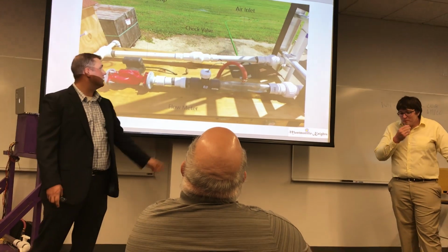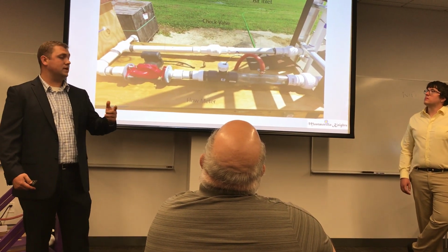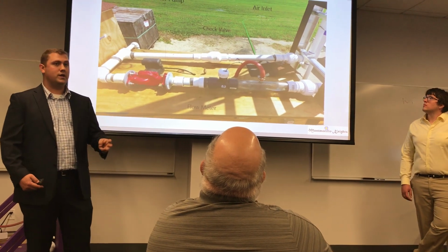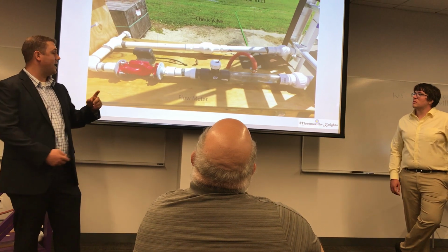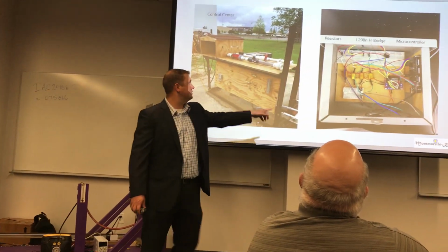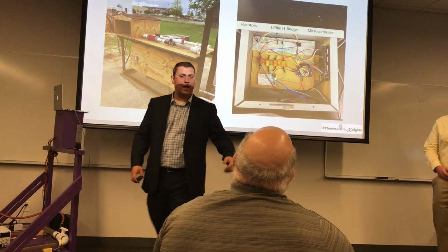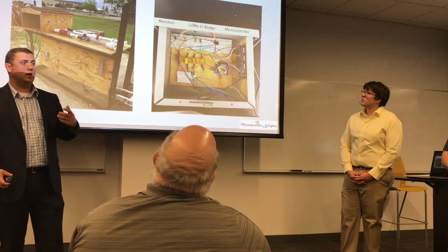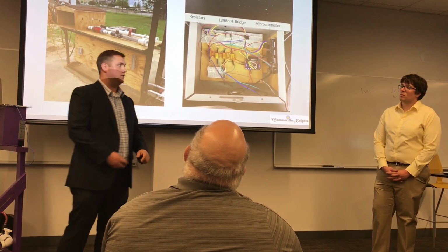and an air injection. Along the side of the PVC pipe on the riser, there's 3 pressure regulators, and all these pressure regulators are wired back to the control module, which is at the bottom in the little doghouse. By wiring it to this control module, the microcontroller, we can hook it to a computer and get real live data while the model's running that we could compare against the CFD.